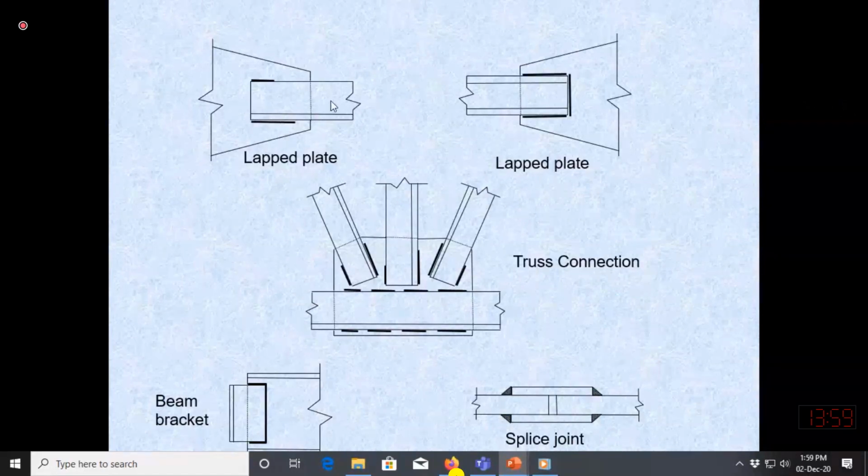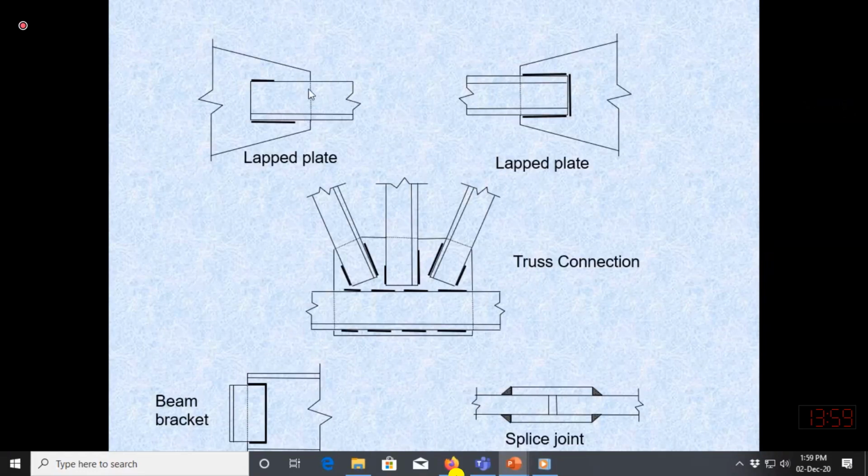So you can say that this is the angle section. The angle section may be welded with this gusset plate. Each member, each connection is designed separately. Here at an interior joint, all the members which are meeting at the gusset plate, we design this connection separately. Here you will see that one length is larger, another length is smaller for the channel. We will discuss why.